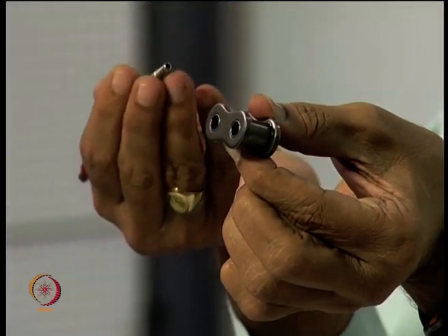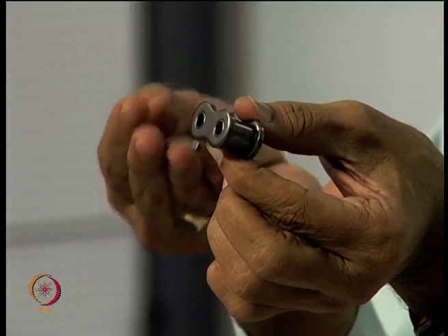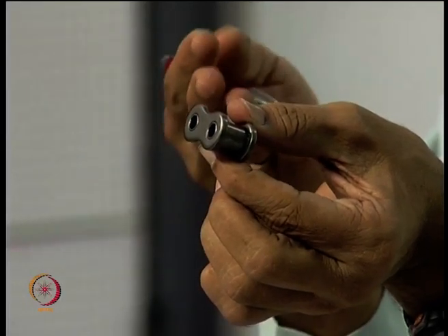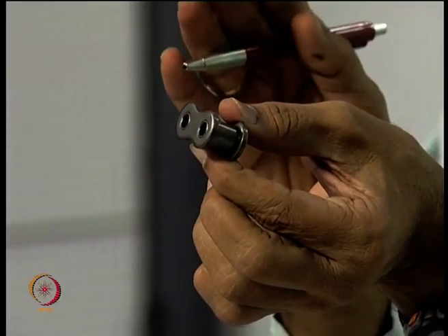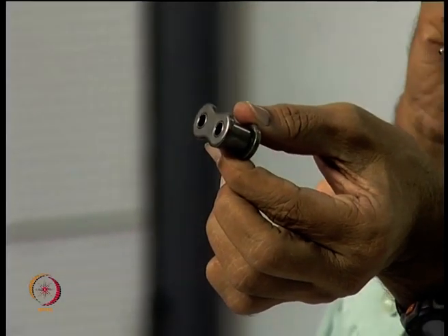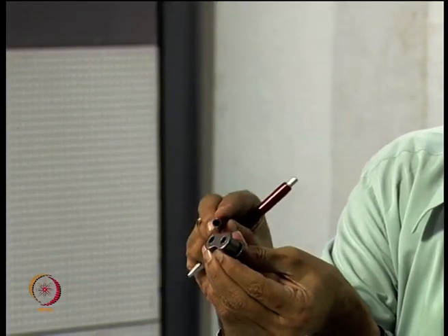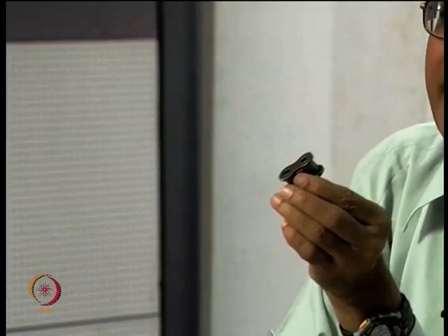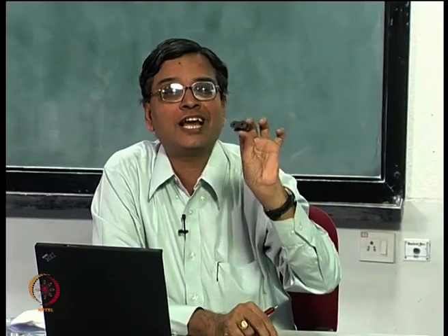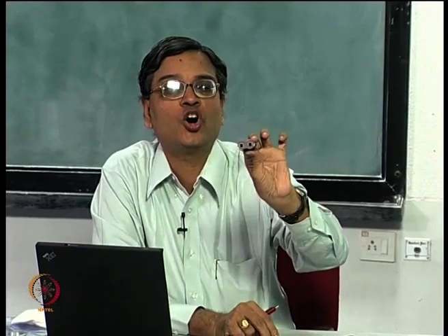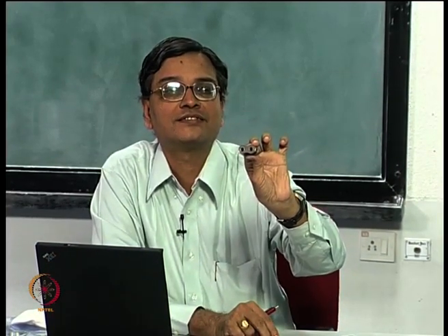Finite geometry I cannot approach by theory of elasticity. Definitely I can approach it by finite elements, absolutely no problem, but there I have to apply the boundary conditions. What I may not know from a production shop is that this may not be perfectly cylindrical, it will have a variation. So, suppose I do an experimental analysis directly on this component, which acts like a prototype, then I capture all the manufacturing variations that have gone into the fabrication of this.